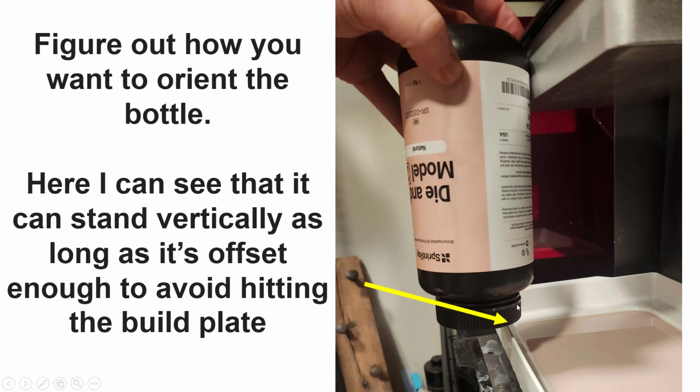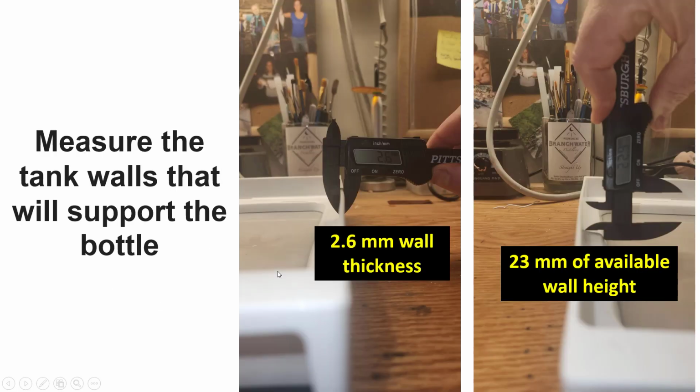And after I took this picture, I thought, well, if I actually pull it out beyond that lip, then you could actually even start a print and be draining a resin bottle. You won't be able to close the lid, but you could actually be printing. And as long as you don't have it in a really bright room, you don't have to worry about the ambient light curing your resin just for the time where you're draining it. So this is how I want to orient the bottle, more or less. I'll probably pull this out here to the left just a little bit, where maybe the edge of this bottle is right even with this tray.